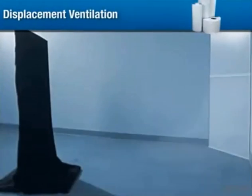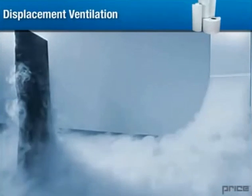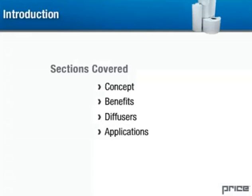Displacement ventilation is a relatively new concept in North America that combines innovative technology with natural forces to distribute air in a space. In this unit, we'll explore the concept behind displacement ventilation, its benefits, and how it compares to other air distribution systems. Once we understand that, we'll look at Price's displacement diffusers, which are varied in shape and size to cover a wide range of applications. We'll learn the importance of properly configuring a room in order to achieve superior air quality and deliver large volumes of air in an efficient way.